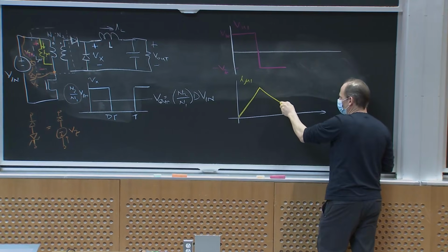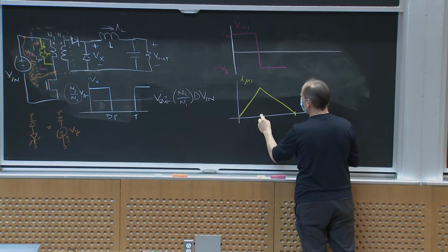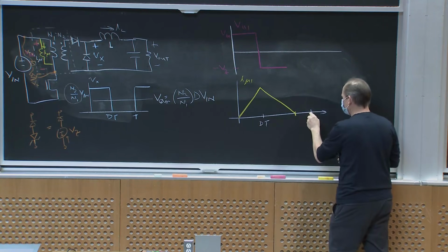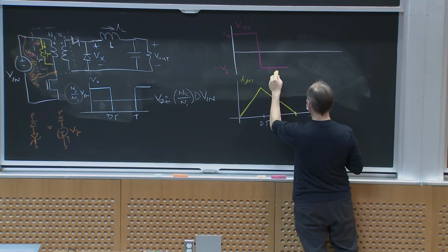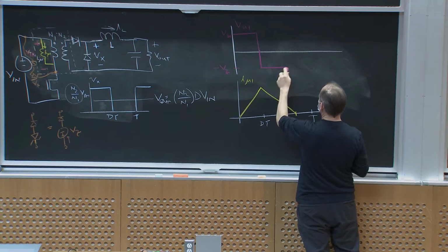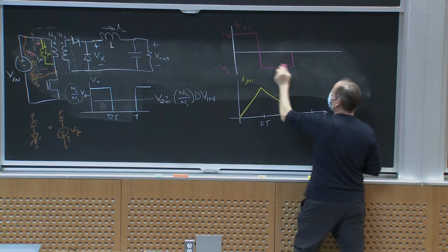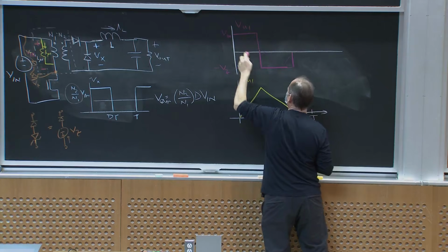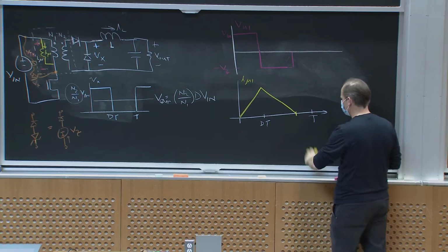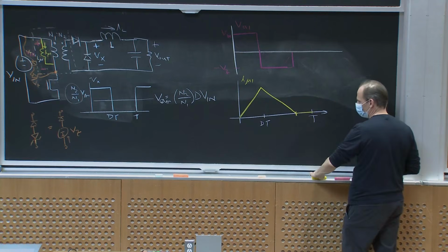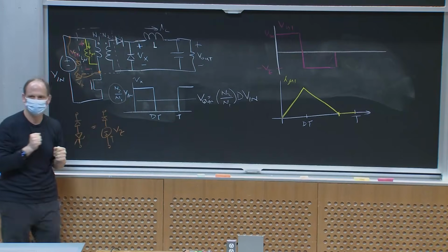And eventually what I would like is for this to hit 0 at some time. So if this is dT, and T is over here somewhere, when would this happen? This would reach 0 basically when the volt-seconds, this area, equaled this area. My net volt-seconds on my inductor would be 0, and then it would just stay 0. The current would have gone to 0 in the magnetizing inductance, and that's fine. And so the transformer is just kind of open circuited at that point.